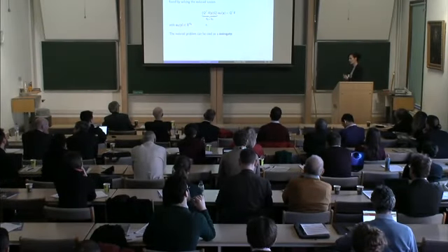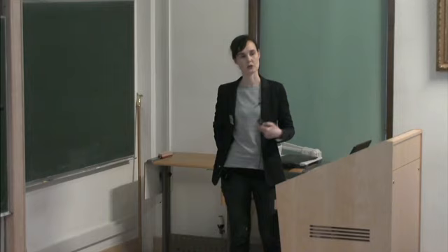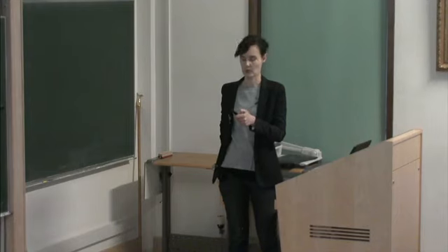I want to quickly query my finite element solution for lots of different choices of my input parameters. If I've got this matrix Q available, if I've spent some time to get this, I can then compute this thing called UR, which will be our reduced approximation, by solving a much smaller system.